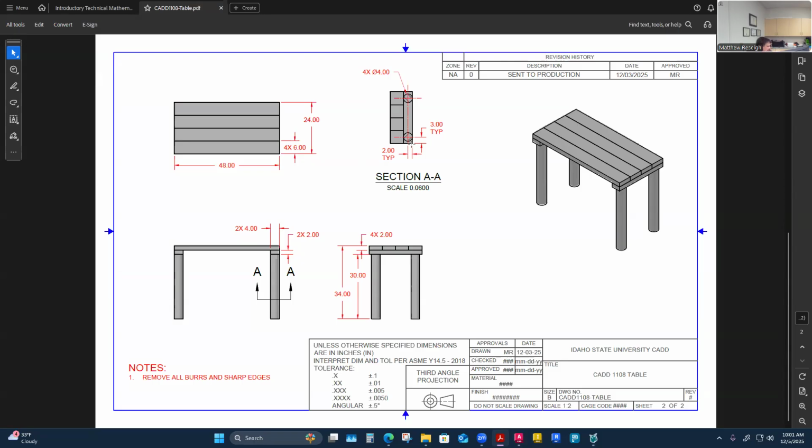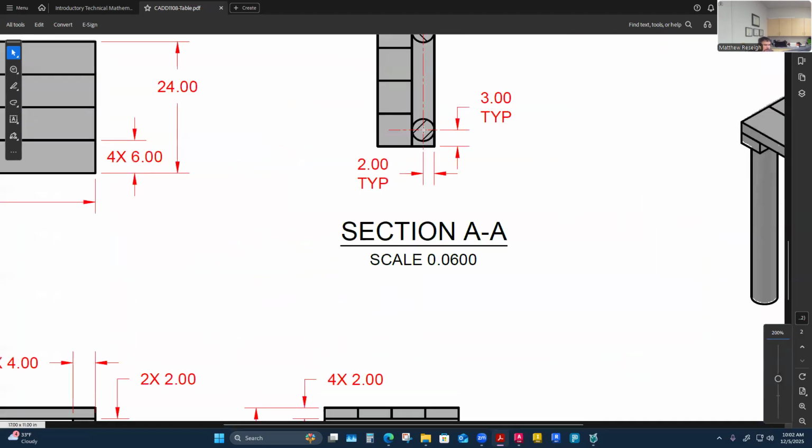So kind of like on our pictorial stuff, I'm going to draw some 2D drawing of that crosshair where the center of that leg would go on the surface that I want it to touch, which is that bottommost surface of those last parts we just drew. So I'm going to come in on that and come in like 2 inches and 3 inches. That's what I'm looking at. Let me zoom in here a little bit. So I'm going to build myself a little grid here, or even I'm just going to draw some construction lines to create this point right here that comes over 2 by 3.